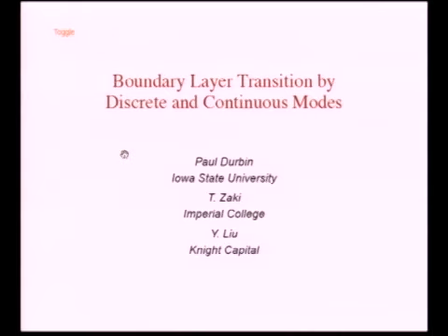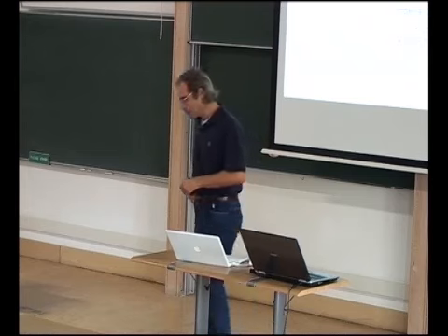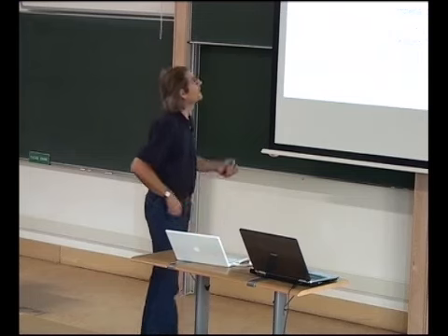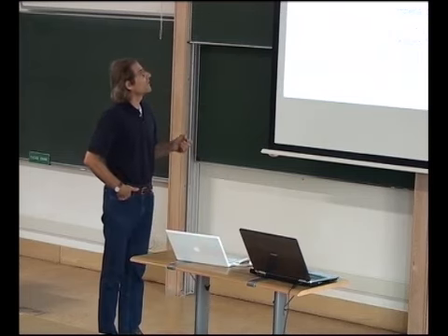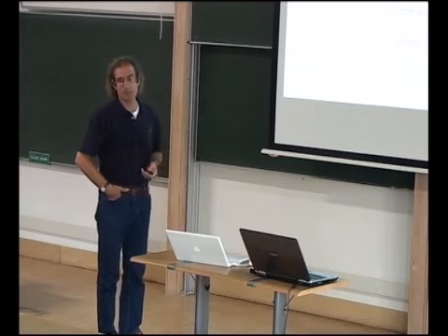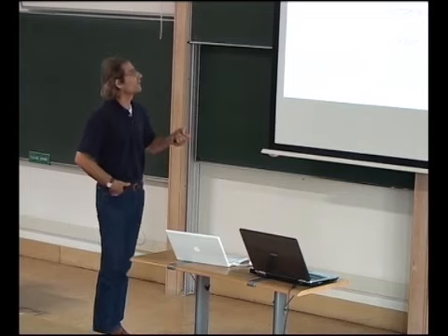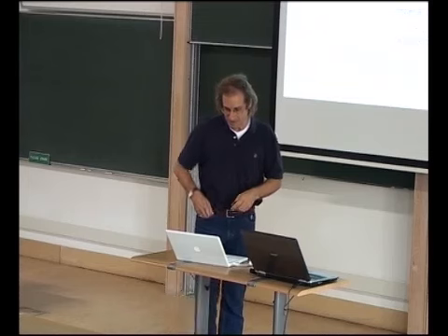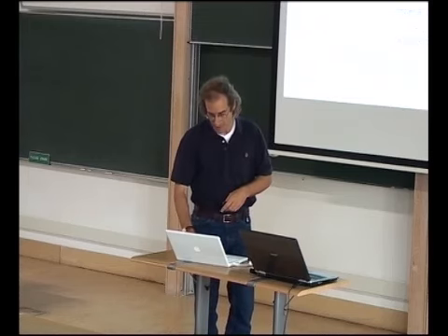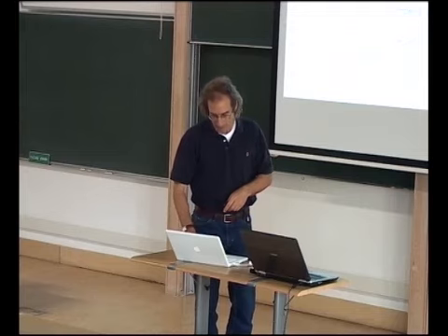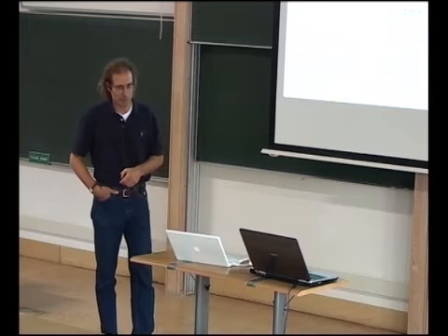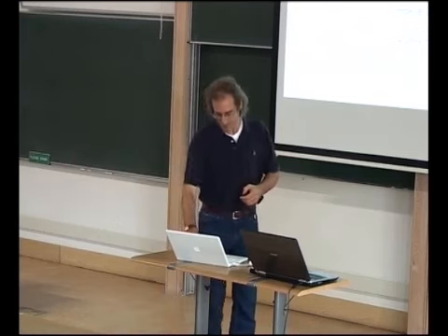The orderly transition and bypass transition. At the last of these workshops on turbulence 9 years ago, Neil Sandham made the comment to me that when people asked what's bypassed, he said theory. So we have our own theory, and maybe other people have their theories, but our theory is pretty much classical, or Sommerfeld theory: orderly transition corresponds to the Tollmien-Schlichting wave by definition, or the discrete modes, and bypass transition can be understood at least in terms of the continuous mode. So our theory is classical or Sommerfeld theory.